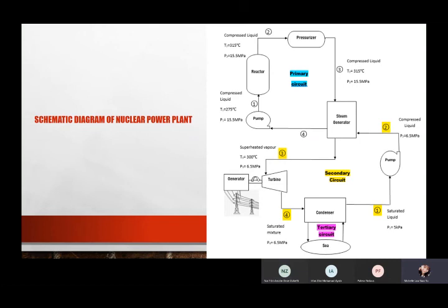The pressurized steam is then fed into the turbine at high speed, which drives an electrical generator connected to the electricity grid network to produce electricity for transmission. After the steam enters the turbine and hits the turbine blades at high speed, the steam loses energy and starts to condense, flowing out of the turbine in a saturated liquid-vapor state with high quality X. The mixture is then cooled down and condensed in a condenser to become liquid and pumped back to the steam generator. The tertiary loop here consists of the condenser and also the reservoir.